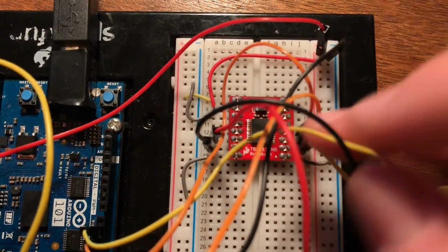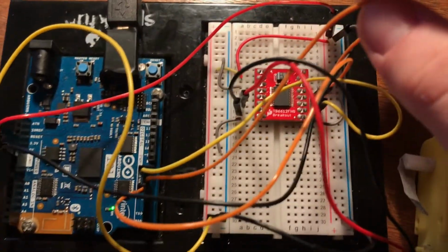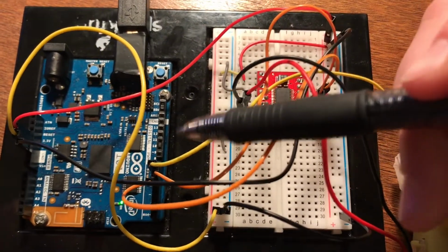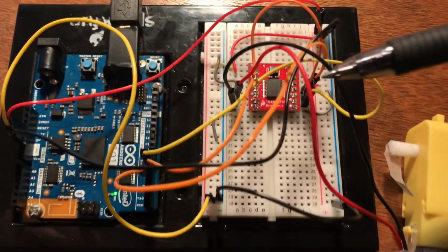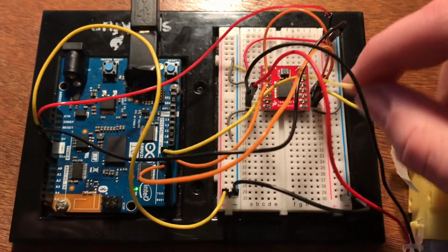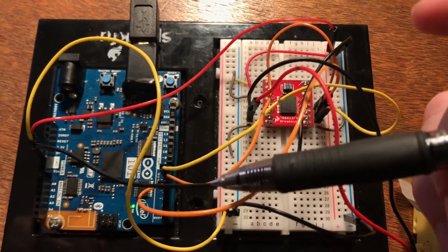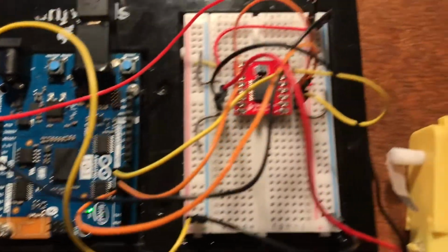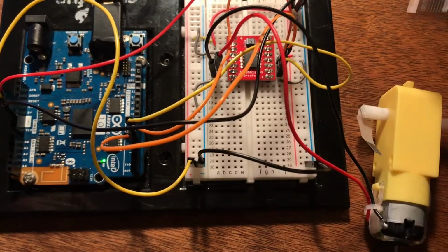This next orange wire here is connected to pin number 5 on the board. It's connecting our digital input pin on the board here to DIR B on this board here. And then this yellow wire here is the PWM pin of the board connecting to pin number 6 on the Arduino. And then it is grounded by this gray wire here by connecting to this negative column.